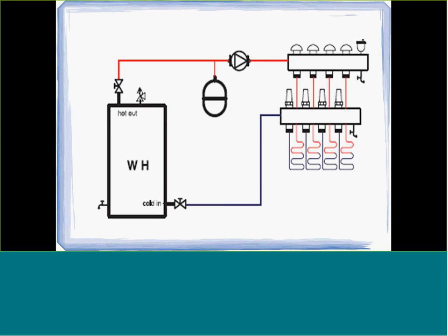We see a lot of these type of jobs come in where they want to use just a standard tank-type water heater on a small garage or an application like that. We dedicate that water heater to the floor heating system only. We put in our boiler accessories, expansion tank, air separator, the fill valves, all that kind of stuff, and we add a pump, run that pipe to the manifolds and out into the floor. And this is a very simple system and can be very efficient also.